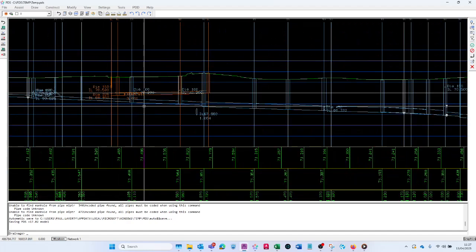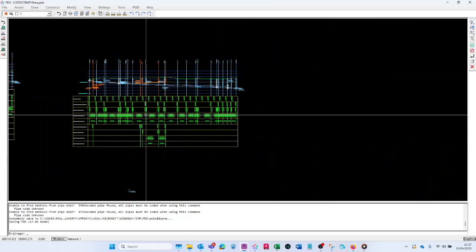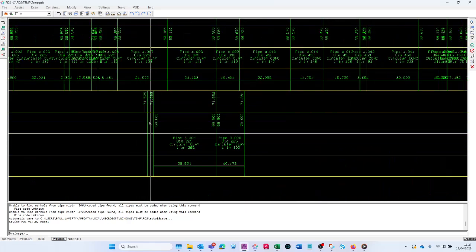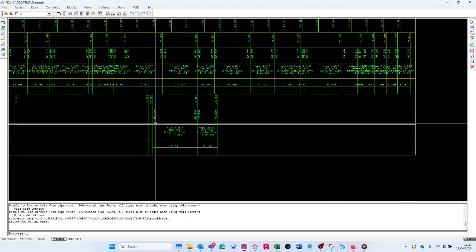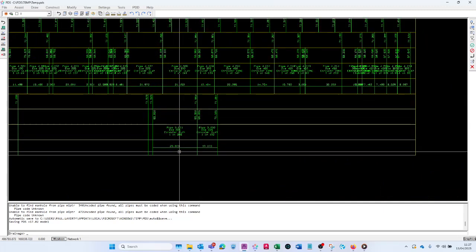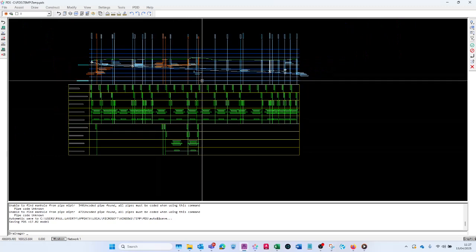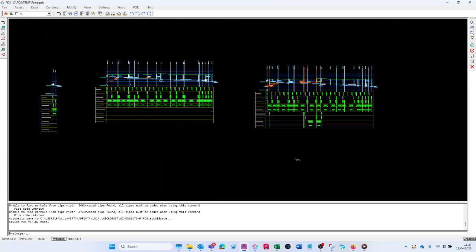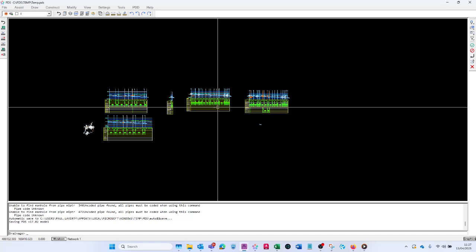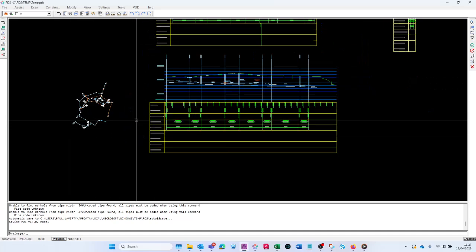And as you can see, if I had the pipe codes, that's really going to start to get messy. Here you have the information: cover level, invert, pipe info, lengths. So those are the ways you can generate the profiles, and that's how you update them. The question is, does this update automatically when you change something in your flow model?